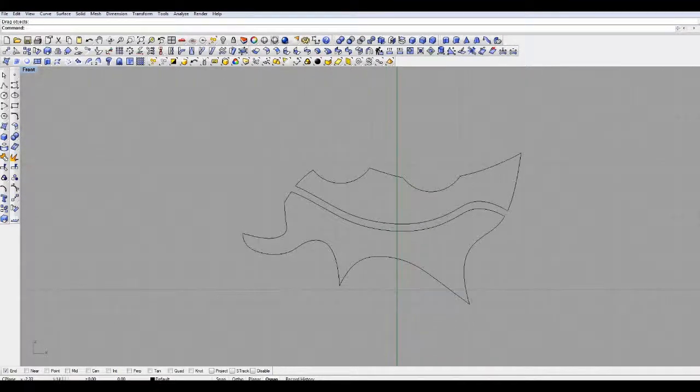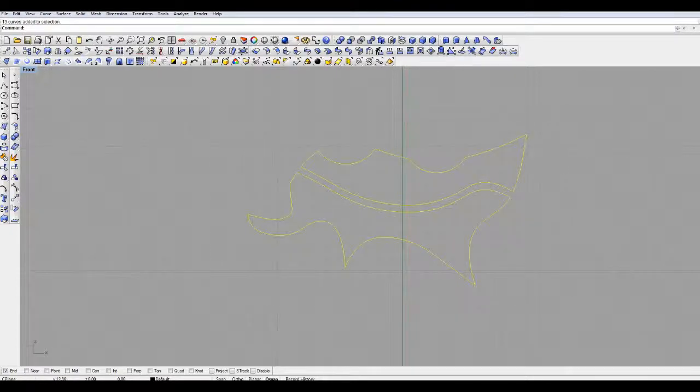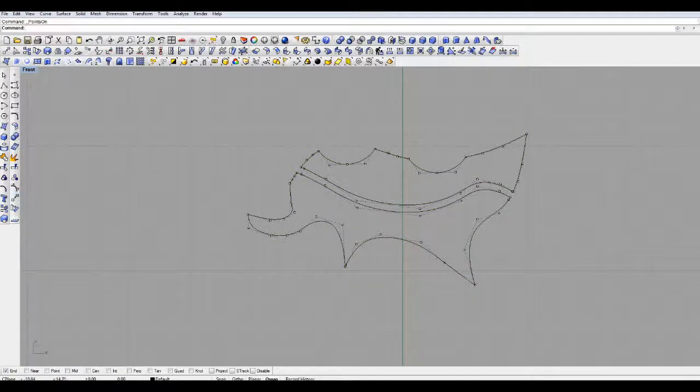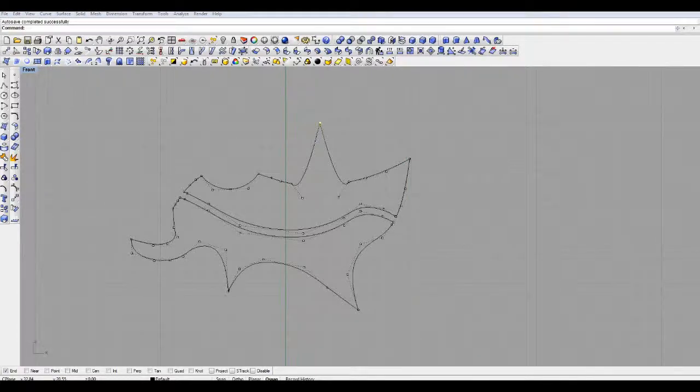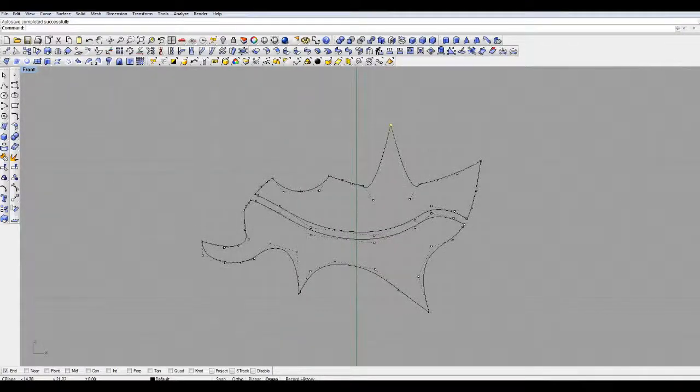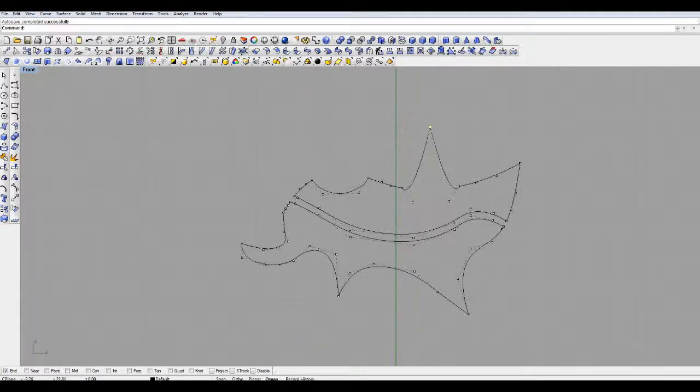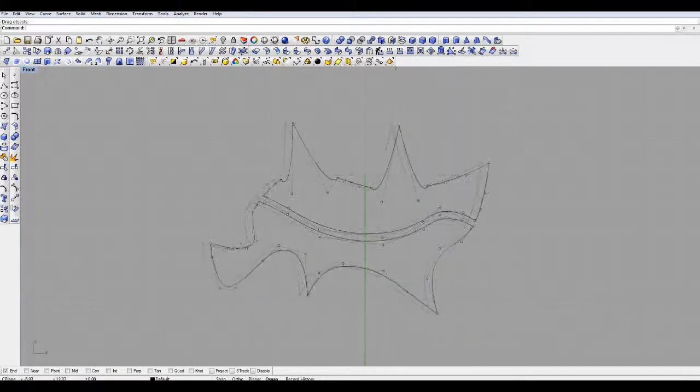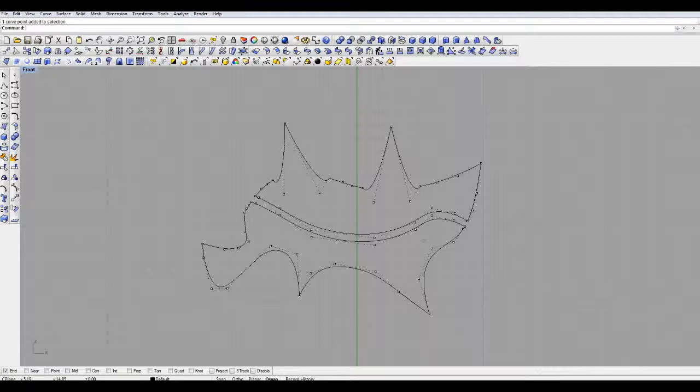And so if we look at our more complex shape here, select everything, control points on. As you can see, since it's much more complex, there's a ton of points on here. So as you can see here, the control point command is really useful for making a lot of really specific edits or manipulations to what you're doing, in conjunction with other things like the split or trim command I just showed you. You can do a lot with the different shapes. Basically, you can make whatever you can visualize and then make it to your specifications. It's quite useful.